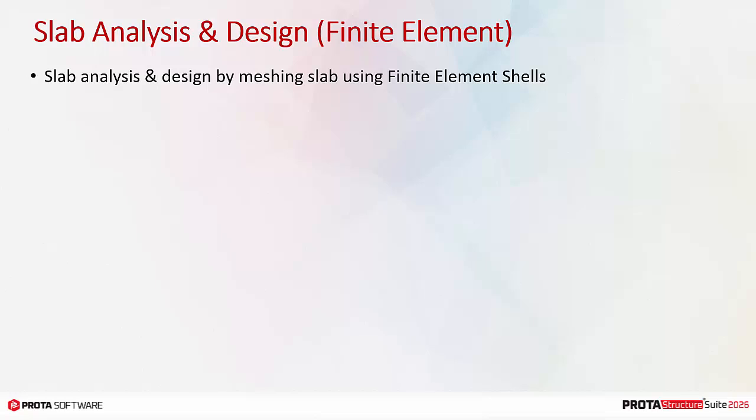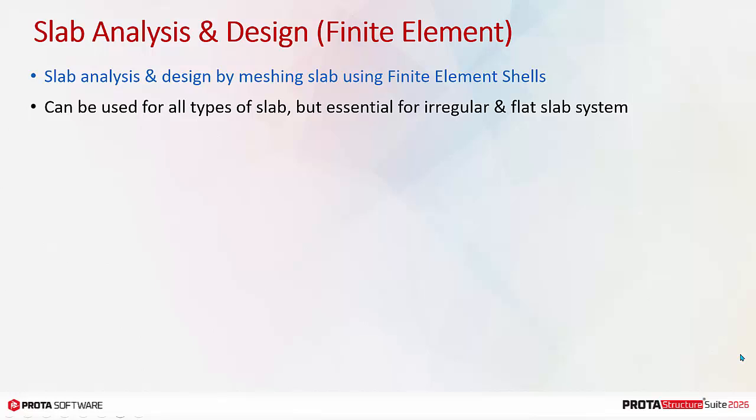Slab analysis and design can be performed by meshing slab using finite element shells. This method can be used for all types of slab, but it is essential for irregular and flat slab system. There are two choices of slab analysis.